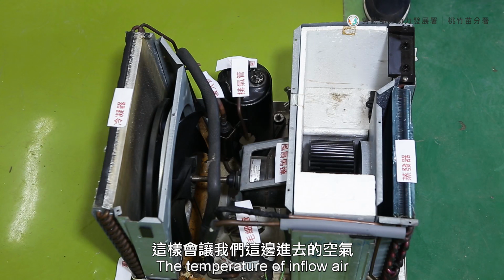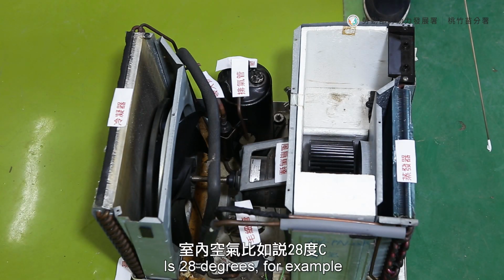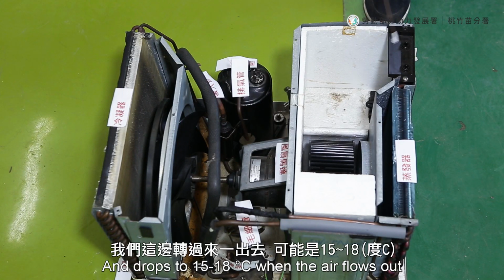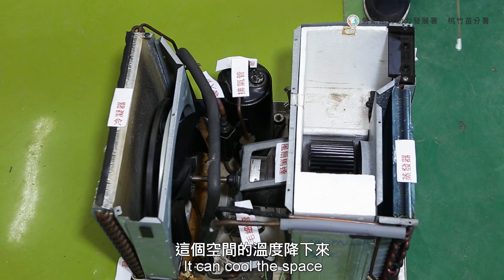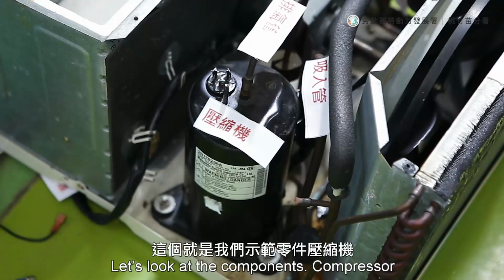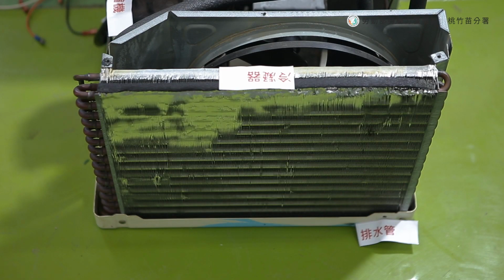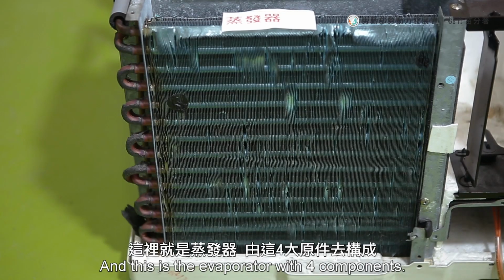The temperature of inflow air is 28 degrees, for example, and drops to 15 to 18 degrees when the air flows out. In this way, it can cool the space. And in the summer, it won't be too hot. Let's look at the components: compressor, condenser, capillary tube, the decompressing device. And this is the evaporator with 4 components.